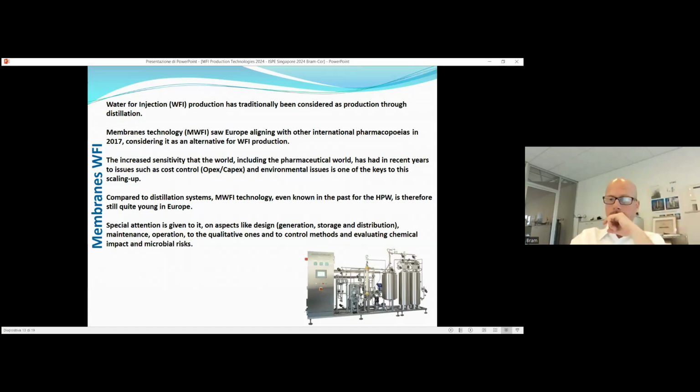Let's say that it is clearly a PW system, as we have seen in the first slide. A PW system normally allows a 1,000 times higher level of bacteria. So the ultrafiltration module at the end of the machine is used to control this kind of bacteria level. But typically we have a PW system at the top of its design with an ultrafiltration module at the end to control the excess of bacteria and endotoxin.